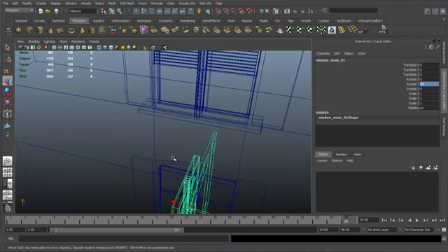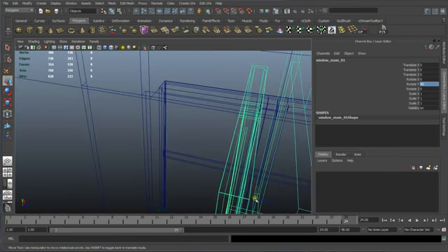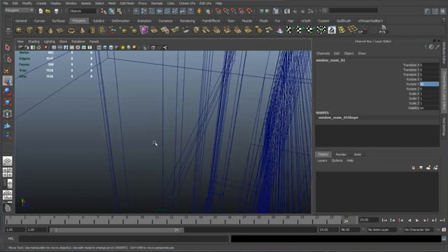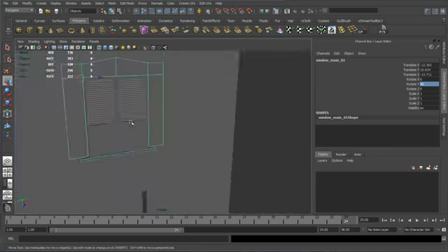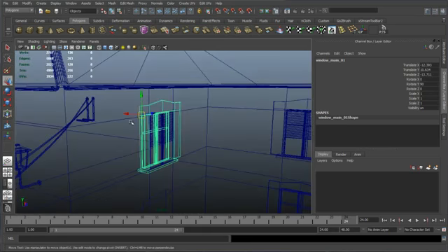So I'm going to duplicate the window and rotate it 90 degrees, the one that we've imported. I'm going to just move the pivot point to the top right corner, just holding D, V and just snapping the pivot point where you want. And this will give me the ability to snap the whole window to this frame of the window. Because I haven't deleted this window that I'm going to place over it, so I can snap to it and then delete it.